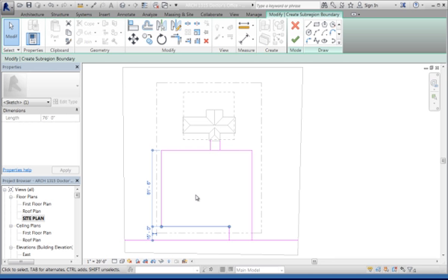It says you'll need 1 parking space for every 200 square feet of building. So depending on the size of your building, if you had a 1,000 square foot building, you would need 5 parking spaces, right? If you have 5,000, you'll probably need 25. Out of those, and this is all written on your assignment sheet, you'll need 1 ADA space for every 25 parking spaces. So first you need to know how many parking spaces you have. Then you need to figure out the ADA spaces.